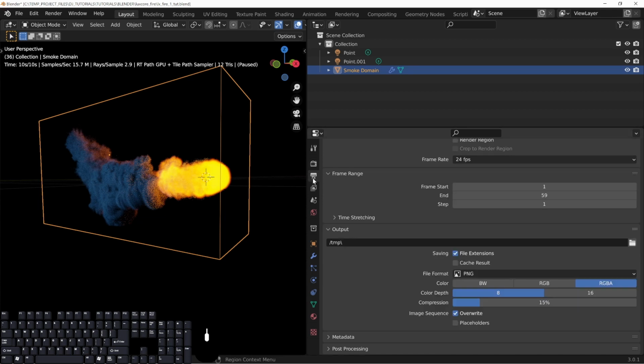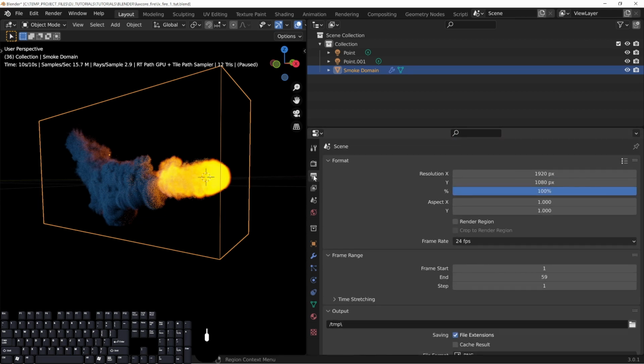And as always, my recommendation is that in your render properties, whenever you set up your camera, change this to 200%, in my opinion. Change it to 200% of whatever your final needs to be, because you'll get a lot more crisp of an image, because in post you can take that image, scale it down to whatever your final resolution needs to be, and it'll look a lot tighter and a lot neater, even if you use fewer samples in your overall render. So that's definitely a step that I would recommend. If you can't handle 200%, change it to 150 and you'll be good as well.